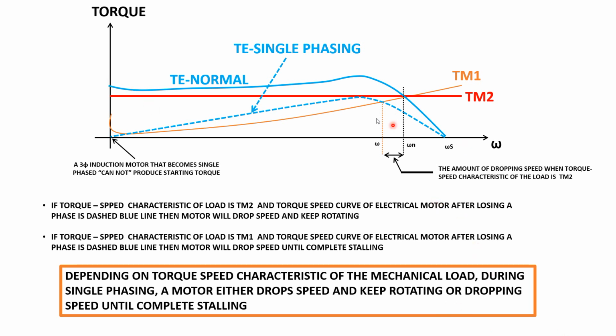This is the torque speed characteristic of the induction motor in normal condition. So what does 25% mean? It used to be here, for example. Now it is 25% less. So when you say 25% less, it means this curve is changed. It's like this dash line curve now.